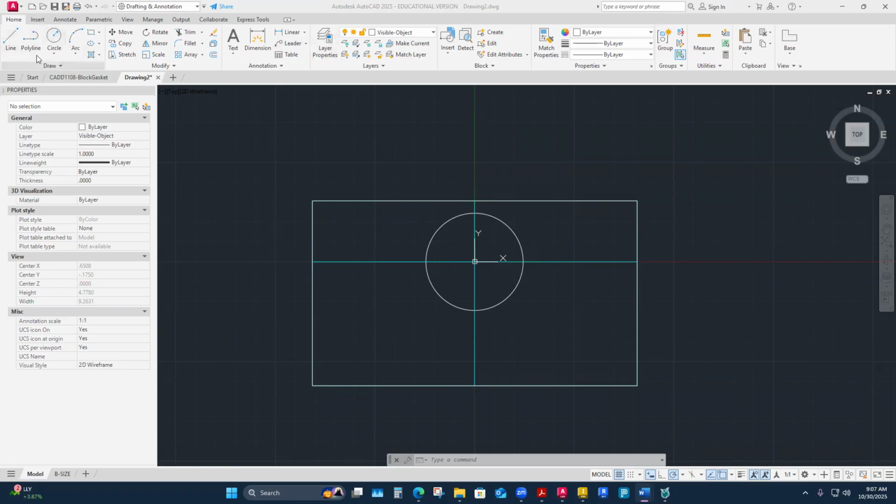We'd like so much of it to be symmetric, but things that you'd obviously expect to be symmetric just aren't exactly. I think it's meant to be a bit of a gotcha, with a lot of dimensions. So when I see something that's pretty busy like that, I look at each feature really closely and place it one at a time, not try to do a bunch of mirroring unless I'm really sure that I can mirror or copy. It'll be a little painful to build it here, but I've got my overall outline.